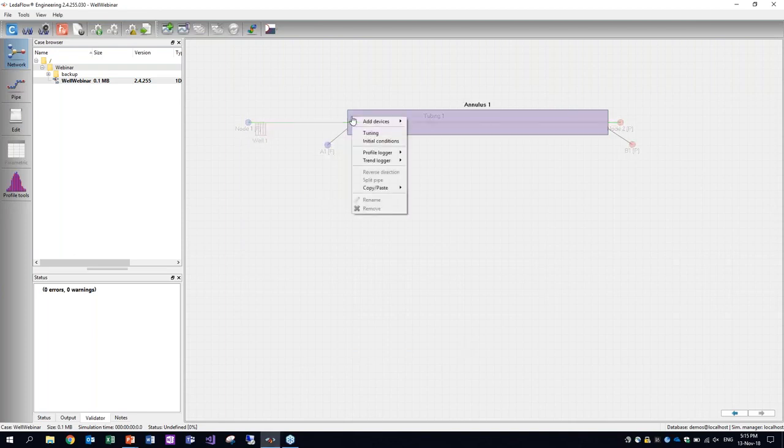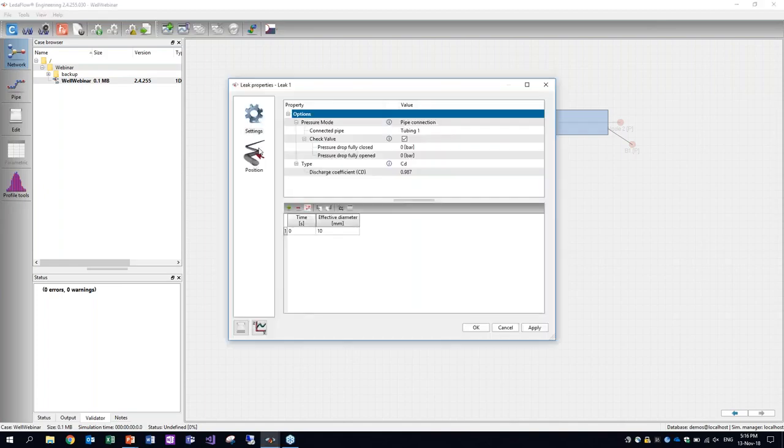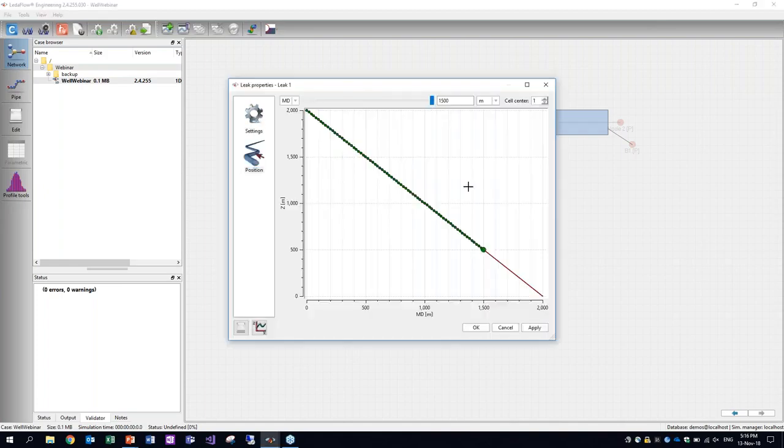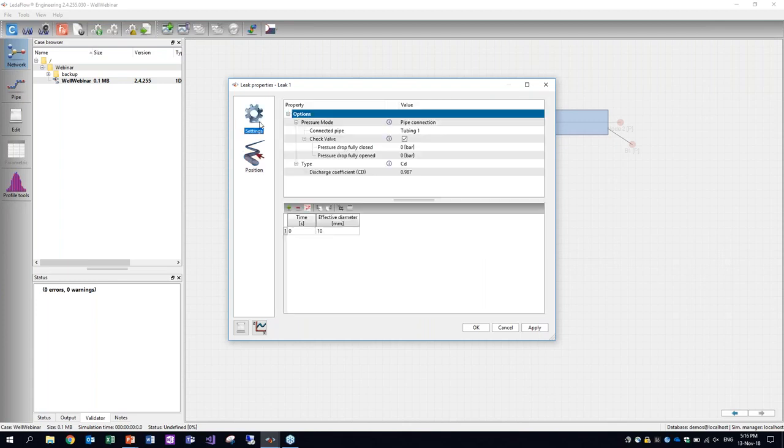And then the second thing I need to do is put in a leak for the gas lift valve. So we're going to put it all the way at the bottom of the tubing. So yeah, if you do any other simulation, it's possible to put it at any height, and also to add more than one gas lift valve in LedaFlow, so you can have multiple, and you can see them opening and closing during the simulation then. But here we're just going to use a single one, and it's modeled as an orifice, so we're not using the gas lift valve tables here either.